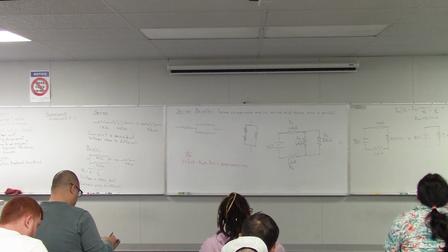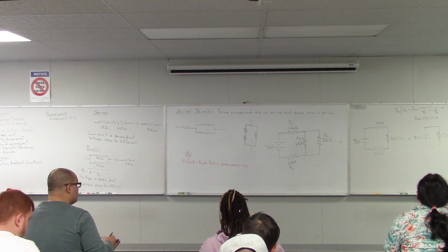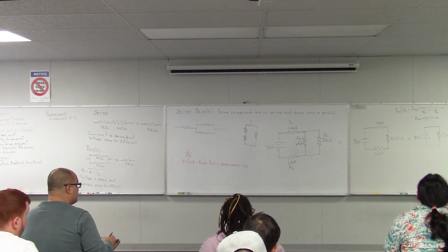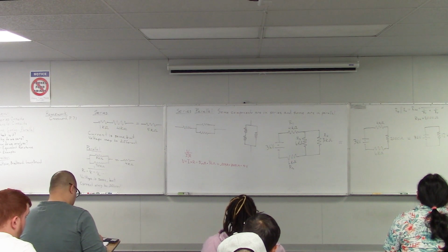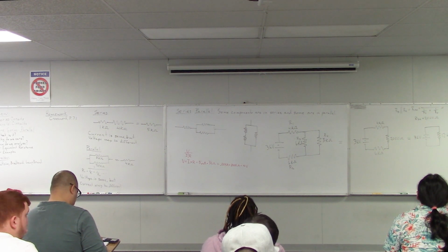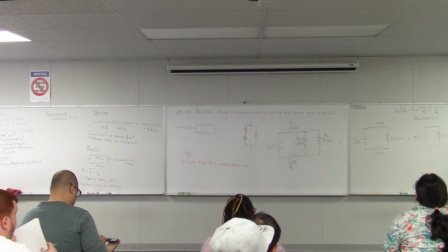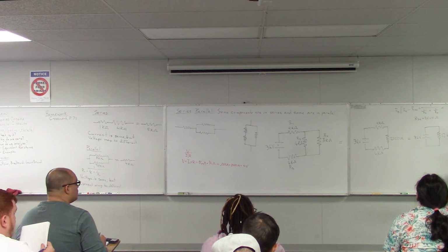And what's our total voltage here? 36 volts, perfect, just the voltage from the power supply. Now what can we find next from here? Total current, that's right, because we know the total resistance and the total voltage.